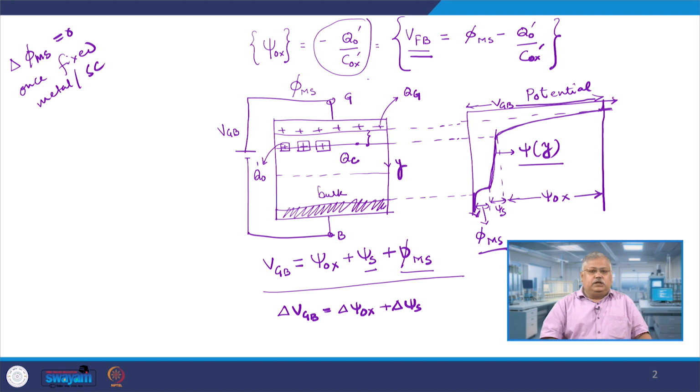The takeaway from all this discussion is, look at the right hand slide, this is the one slide which I want you to refer to, and that will be your important slide before we shift topics. The surface potential is a rising potential as you move from the bulk towards the surface. It rises until you reach the silicon dioxide interface, where it is at its maximum.